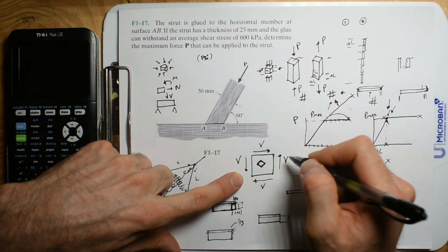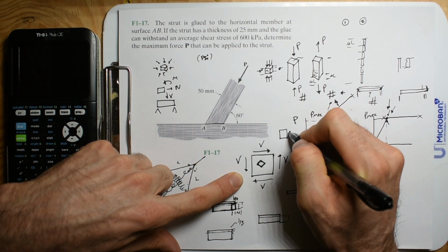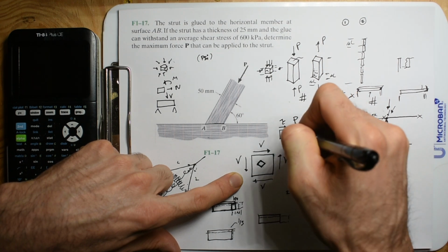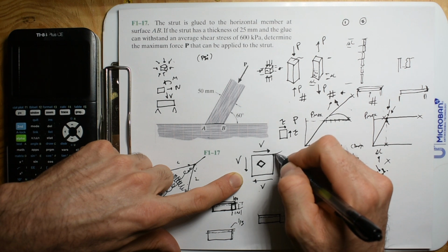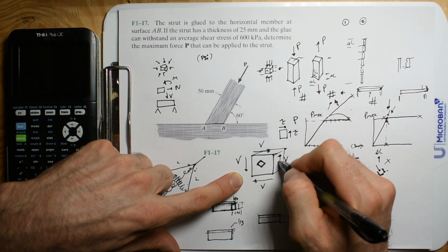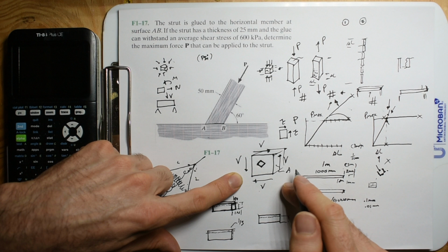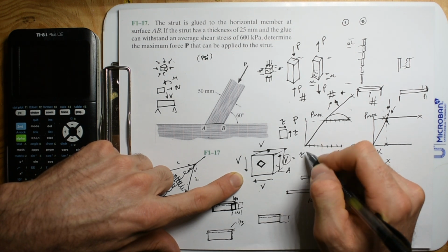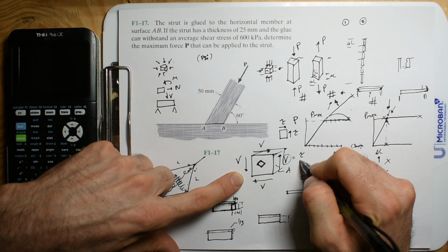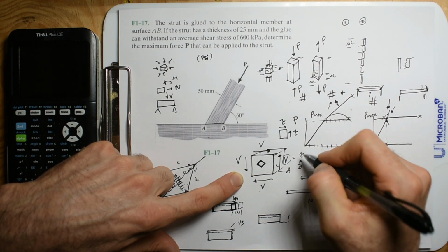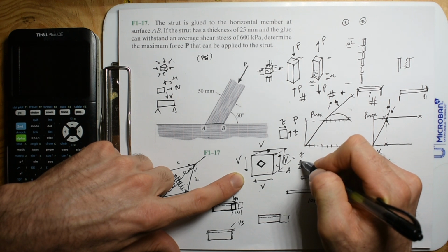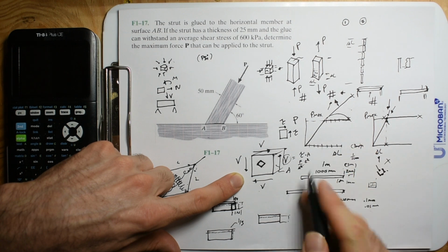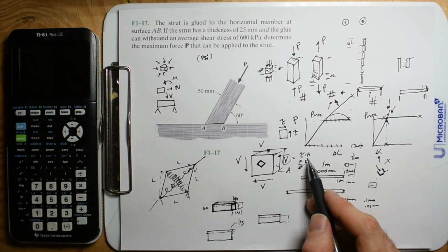and they don't even show it like forces. They just say, hey, this isn't even a force yet. It's just a shear stress. So it's a pressure, and this face has some sort of area. It's a 3D block, so if you did have area on this face, then to find the force, that shear pressure is force per length squared, PSI, newtons per meter squared, or pounds per square inch, and then you multiply by the area, length squared. So then the units cancel and you get force.